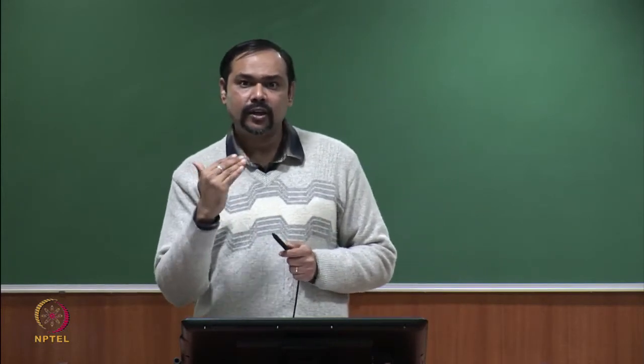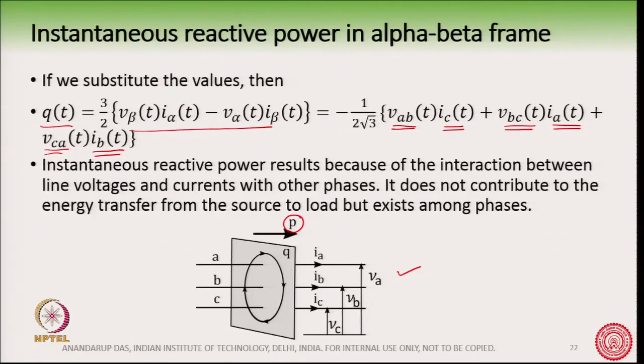We usually make them coincident, they come over each other, and there is a perpendicular 0 axis. So, that is the visualization part. In case of an unbalanced system, you have alpha, beta and 0, so the space vector is rotating in a 3 dimensional space. Okay. And we also defined the powers, Pt and Qt, which are instantaneous active power and instantaneous reactive power.